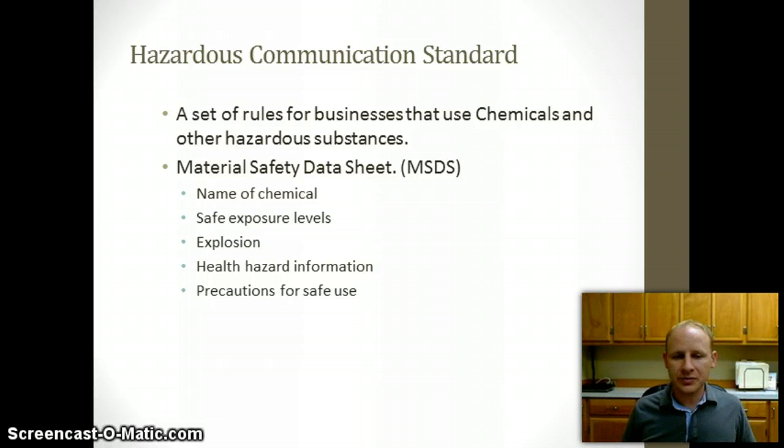So even if you think about a high school industrial arts or technology education teacher who teaches some cabinet making and they finish projects, do some finishing, in those shops it's very common to find some lacquer, polyurethane, different stains. All of those have specific MSDS sheets, and those are supposed to be on file. Most importantly, they provide the information on safe exposure levels, explosion levels, precautions for safe use, and what to do in an emergency. So they're important to have. Every business owner is required to have those on file and ready to go and communicated to their employees.